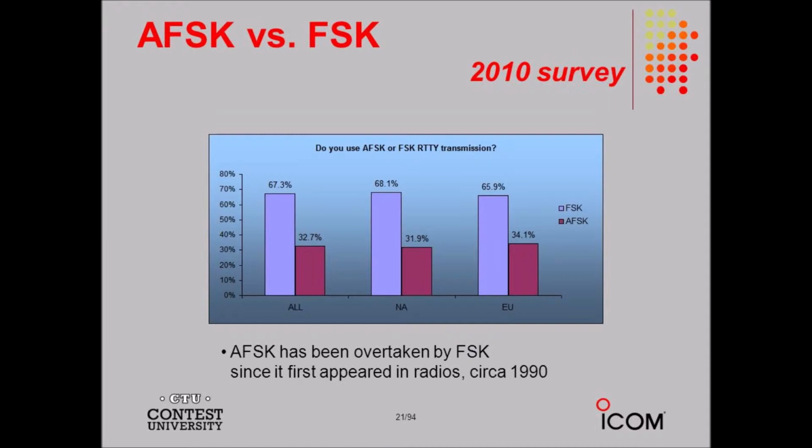In radio teletype, or TTY, FSK and AFSK systems, a terminal unit, TU, converts the digital signals into electrical impulses that operate a teleprinter or display characters on a computer screen. The TU also generates the signals necessary to send TTY when an operator types on a keyboard. A device that sends and receives AFSK is sometimes called a modem, an acronym that stands for modulator-demodulator. A modem is basically the same as a TU. Figure 25.1 is a block diagram of an AFSK transmitter.